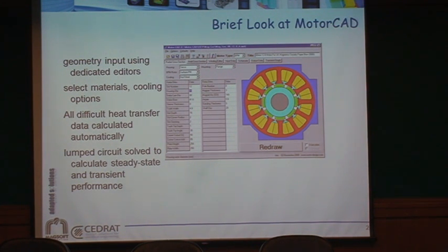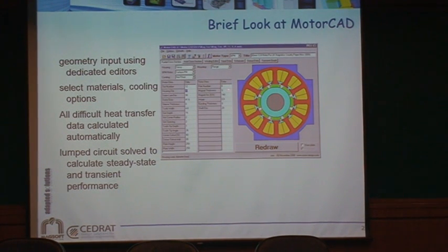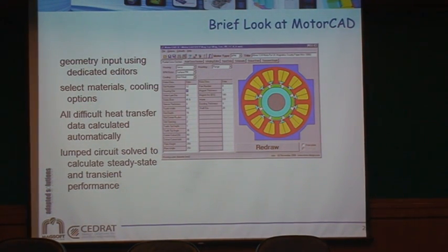And by the way, you can actually bring in the lamination from Speed directly inside Motor-CAD, as well as, we will see, the losses and everything. So this is the template to define the geometry. And you can see the same type of information as we saw this morning: the slot number, the housing diameter, the magnet thickness, the pole number.